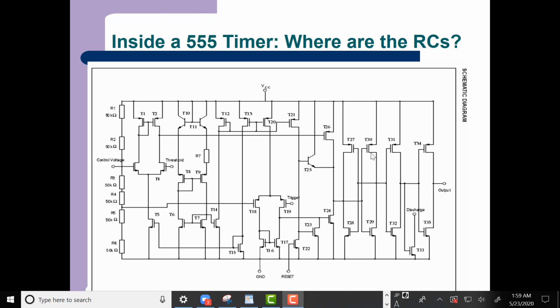But the first stage of looking at a complex amplifier and trying to figure out what it's doing is to divide the amplifier into stages. And it turns out that between each stage, you have a pole. So that's the first thing. That simplifies the problem quite a bit. In between each stage, there's a pole.